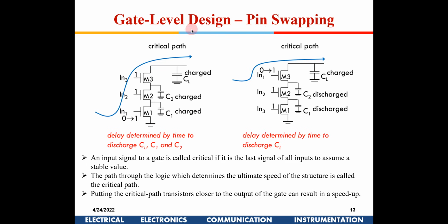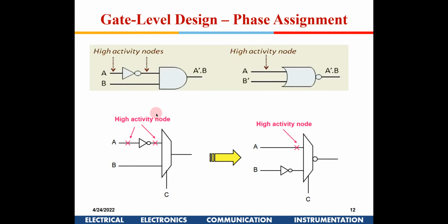Okay, and this is another thing which you might have learnt in your VLSI class, right? What did we learn in the VLSI class? If we want the delays, this is the pull down network of a circuit. So only the NMOS is shown here. This is the output node. These are the pull down transistors which are connected in series, probably a 3 input gate.